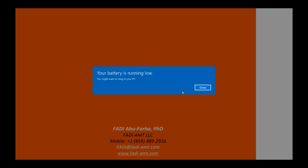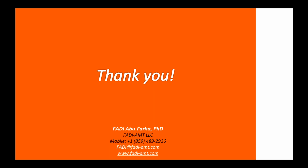Let's say someone wants higher accuracy and wants to capture this effect without it affecting the results. Then you use a telecentric lens like the one shown in our slides, also by the Spectral system. A telecentric lens is specifically designed for this purpose, so that any change in depth, or change in Z, is accounted for in a 2D measurement.